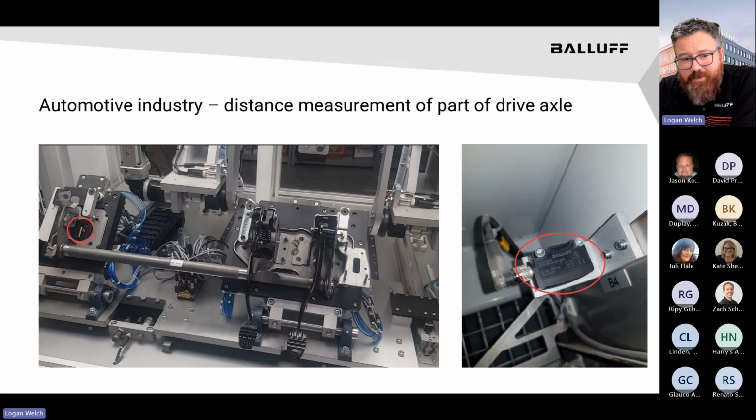In the past, a lot of people have used linear position and linear transducers to measure exact quality checks in an assembly or welding or a process like that. What we've seen a trend go to is using photoelectrics in some of these to detect exact placement, the position of knockout holes, or if a bolt is present or not present before an automated nut goes